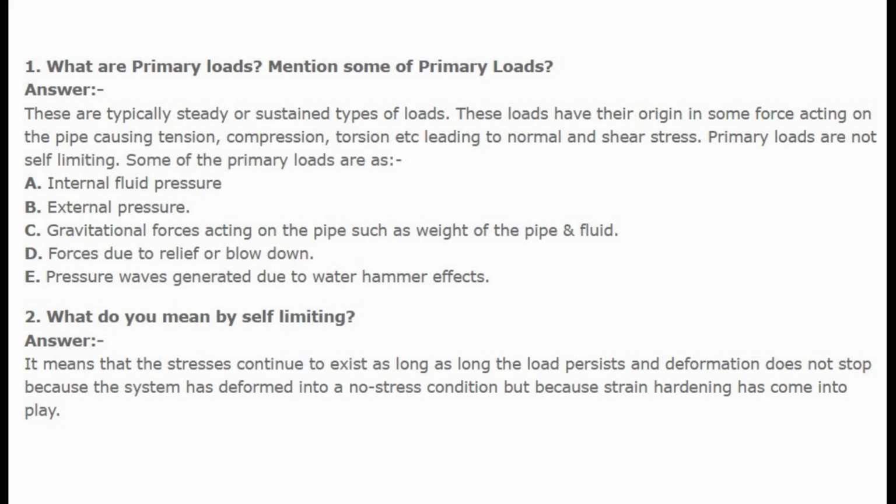Some of the primary loads are: A. Internal fluid pressure. B. External pressure. C. Gravitational forces acting on the pipe, such as weight of the pipe and fluid. D. Forces due to relief or blowdown. E. Pressure waves generated due to water hammer effects.